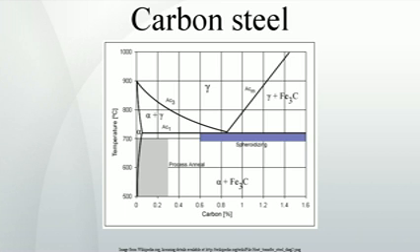The term carbon steel may also be used in reference to steel which is not stainless steel. In this use, carbon steel may include alloy steels. As the carbon percentage content rises, steel has the ability to become harder and stronger through heat treating. However, it becomes less ductile. Regardless of the heat treatment, a higher carbon content reduces weldability. In carbon steels, the higher carbon content lowers the melting point.